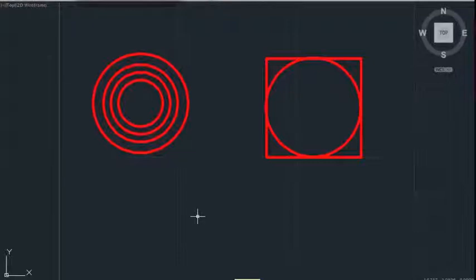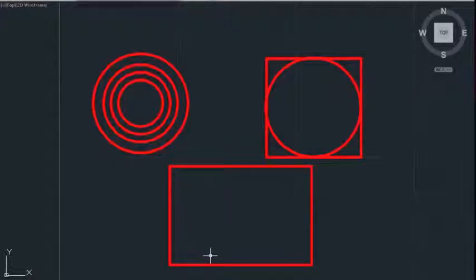See that? Alright, the third object. Again, we're going to use the REC rectangle command. Specify the first point, which is here. Do the dimensions, D for dimensions, because it says it right here. And I know what my dimensions are. Length is 4.8, and the width is 3.2. And it pops up. Perfect.